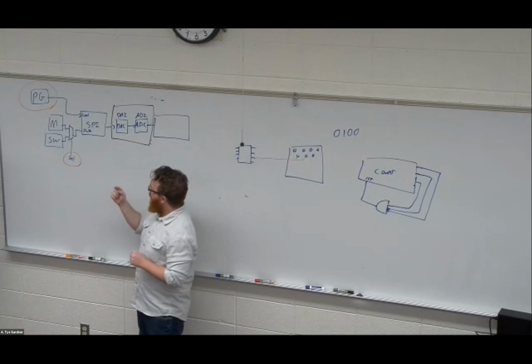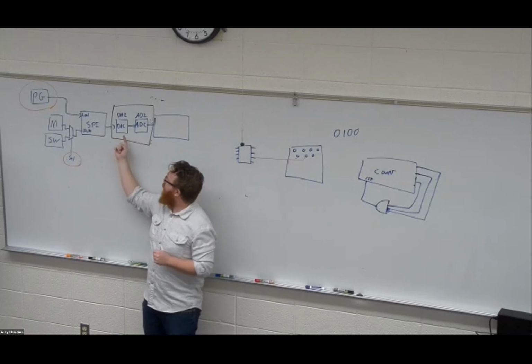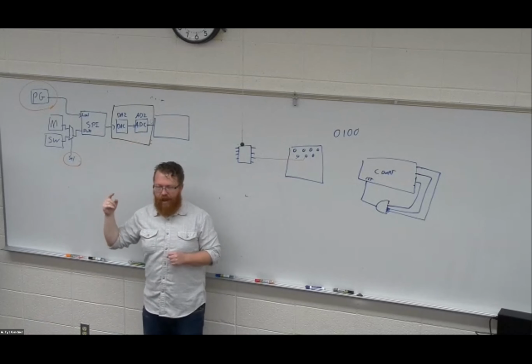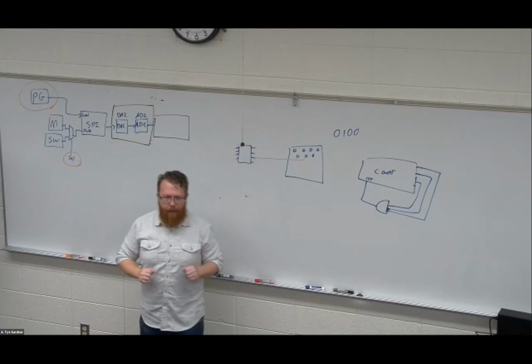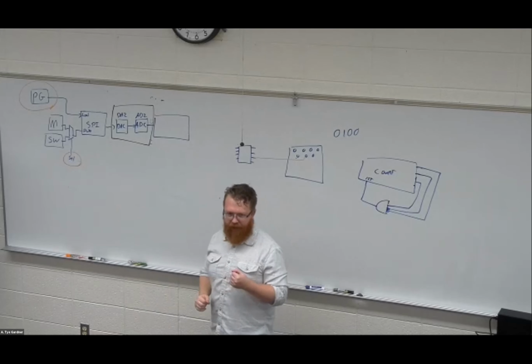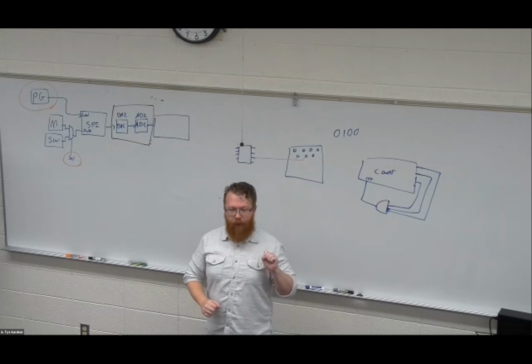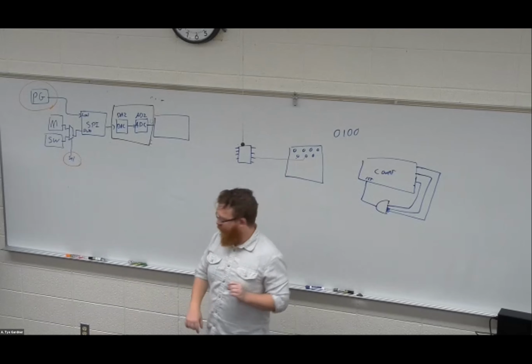And I realize that, oh, I've already done all this work. I don't want to use the SPI, but now I've got to the ADC. I only have a couple wires left. I only have like 4 wires left for my IOs. SPI isn't going to cut it, right? There is a protocol that works fine. It just is slower, right? That's the game of the trade-offs. I can use fewer wires, but it's going to slow me down.